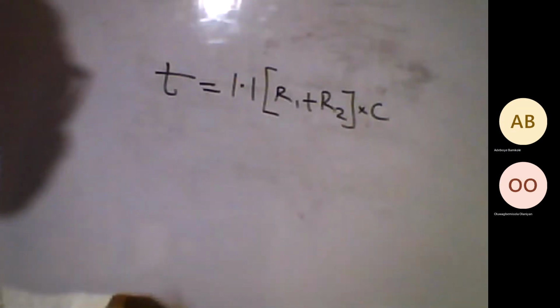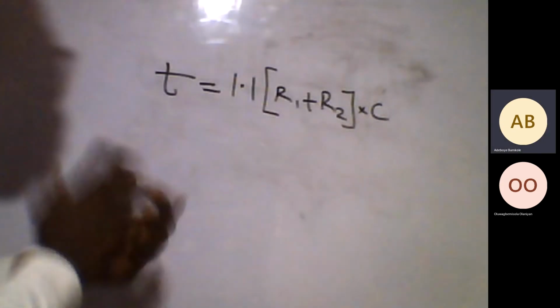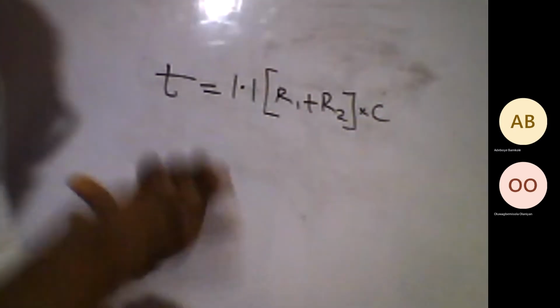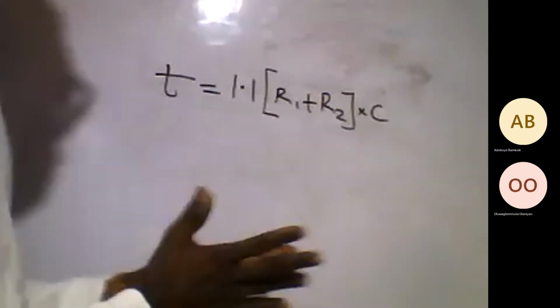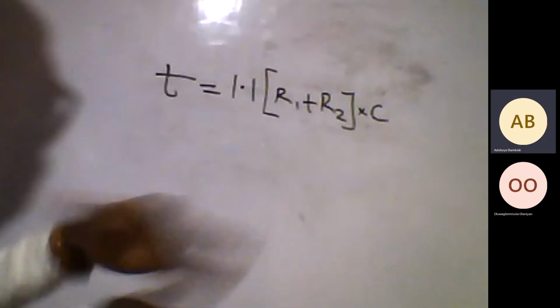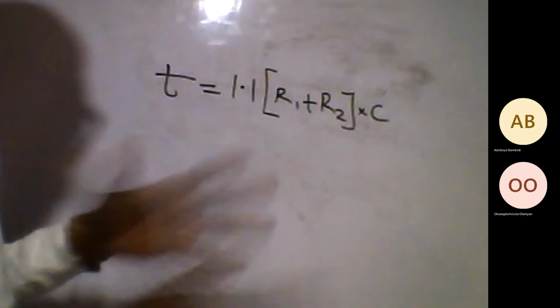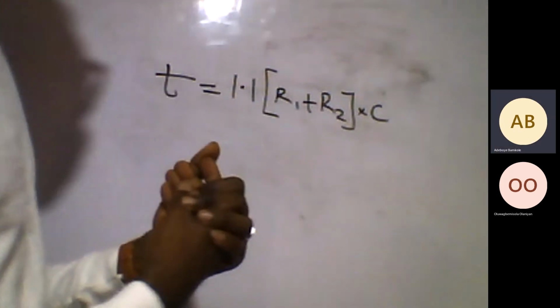Okay, thank you for noticing. C1 is the one that is useful for our timing. C2 is actually not compulsory. It's just to provide stability for the circuitry. If you like, don't use C2. In fact, you can even remove it, but it provides stability.